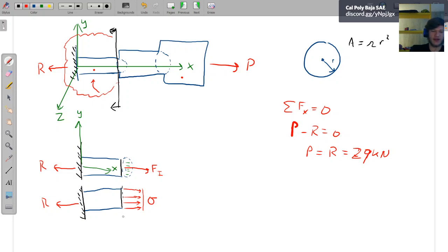And we can calculate a small displacement when we know a stress. So just for this section, just for section 1, we know the internal stress, we know E, we know A, and we know the length. So that's all we need. We say U equals PL over EA.